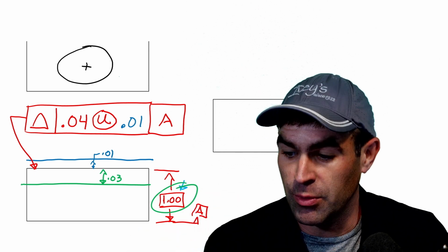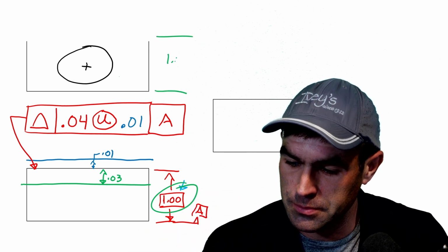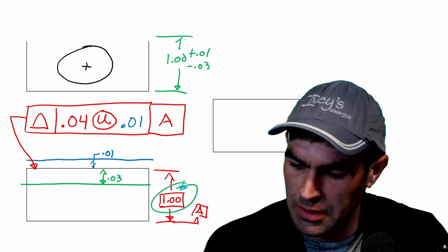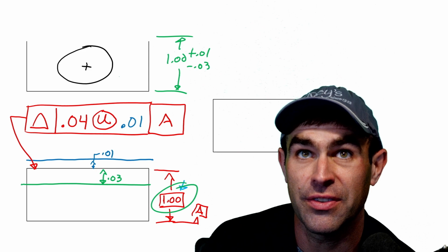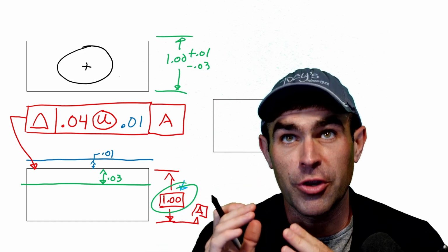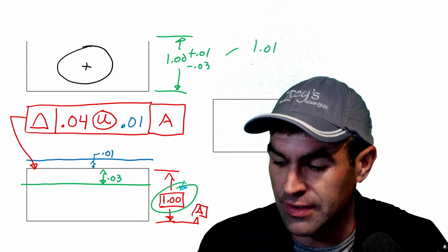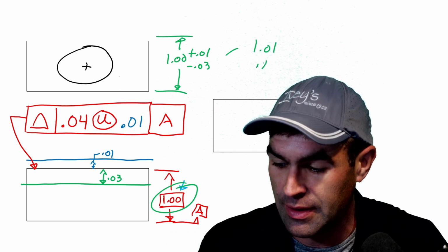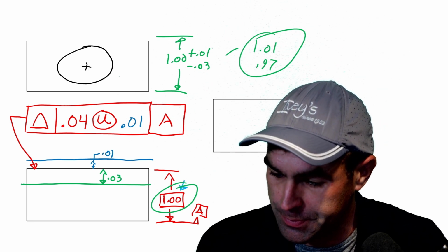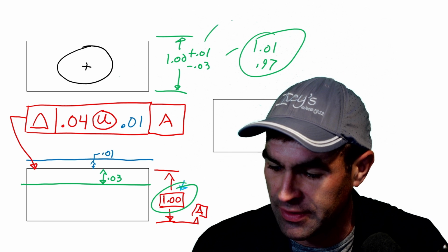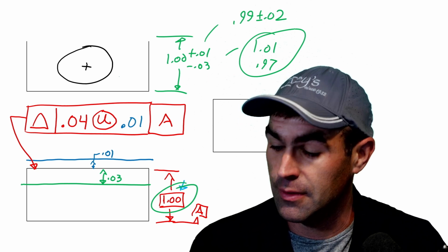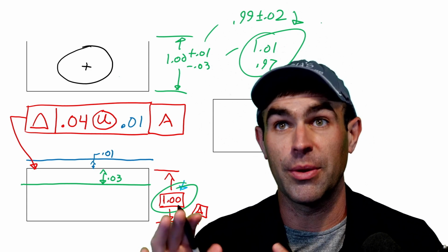So just like when you apply, if we applied 1 inch plus 10 minus 30, which is equivalent somewhat to this profile as far as a plus minus dimension can be, your limits are still whatever this is, 1.01 and then 0.97, no matter how we decide to show that on the drawing. So if I wanted to change this, I could rewrite this dimension as 0.99 plus or minus 2, right? And my limits are still this, right? So just something to keep in mind there.